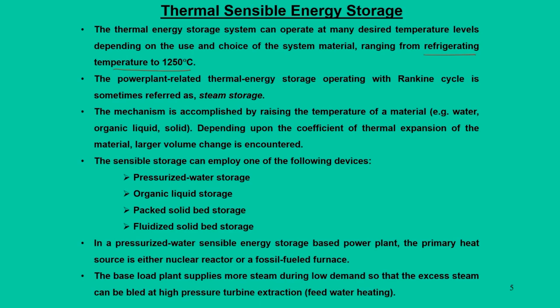For that, one possible method is pressurized water storage, which is nothing but what we call steam storage, and it is very common in large scale power plants. Other methods involve organic liquid, packed bed, solid bed storage, and fluidized bed storage. These pressurized water based systems we call steam storage. This is similar to the case where we store air to run an air turbine. Here we store steam with certain techniques, which can run the peaking turbine at the time of need.